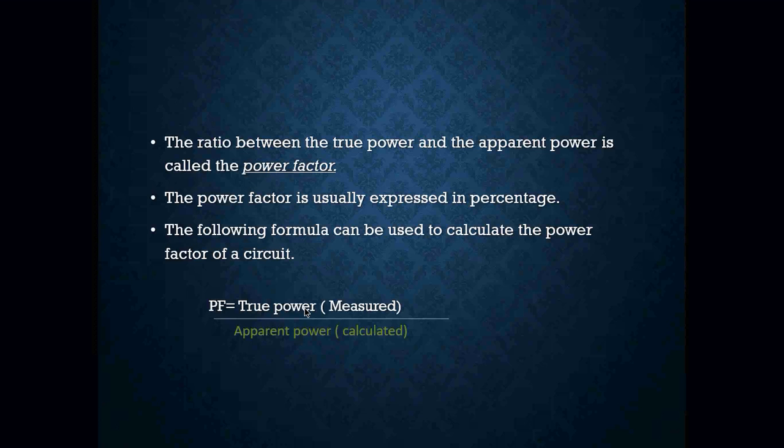Okay, the power factor is usually expressed as a percentage. The following formula can be used to calculate the power factor of a circuit. Okay, your measured power divided by your calculated power.